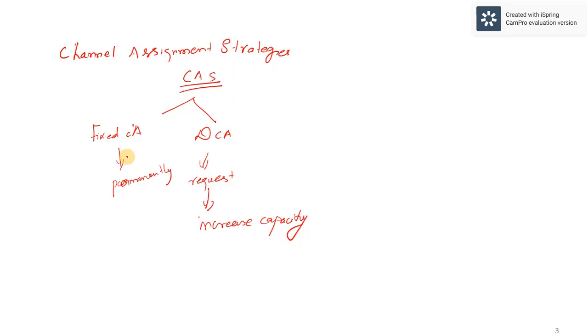Coming to dynamic channel assignment, the voice channels are not allocated to different cells permanently. Each time a request is made, the base station requests a channel from the mobile switching center. The MSC allocates a channel to the requesting cell using an algorithm that takes into account the likelihood of future blocking. The reuse distance of the channel should not cause interference.